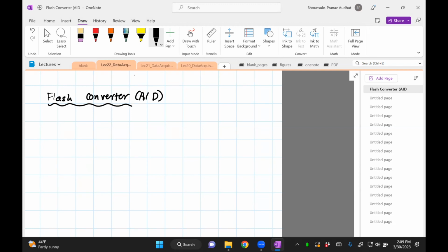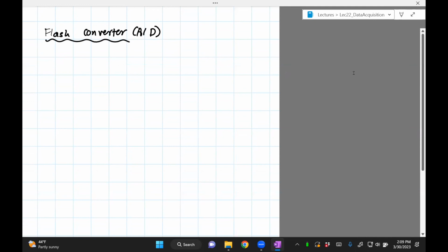Yeah, draw the circuit first, and then we'll look at how it works. This example is going to cover a simpler version. It's going to do a 2-bit A to D converter. By 2-bit means it can only accept 2 bits, 2 places. So it only can go up to 3, 0, 1 to 3. And if you want to go 10-bit and all, you need to add more logic gates and flip-flops, as I'll show you. So, 2-bit A to D converter.